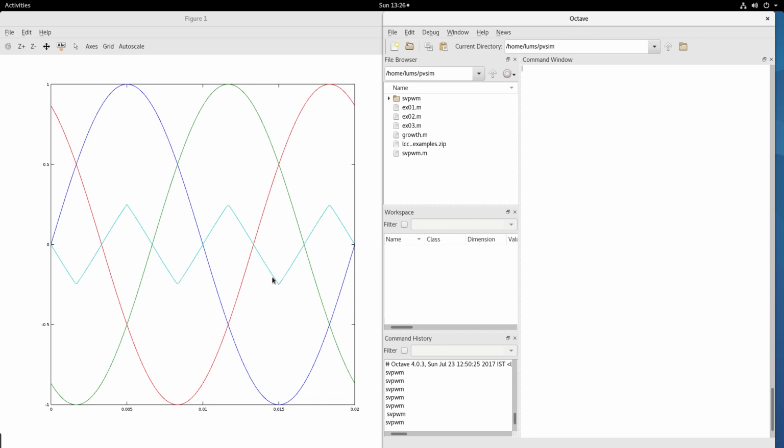Now this wave shape is actually a third harmonic. You will see that there are 3 peaks within a cycle, so that is a triplen. So I have the triplen here. Now what do I do with this triplen? Let us say I have the fundamental. This is the fundamental minus this triplen.